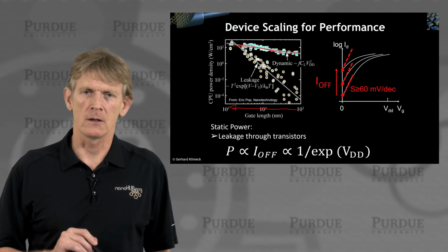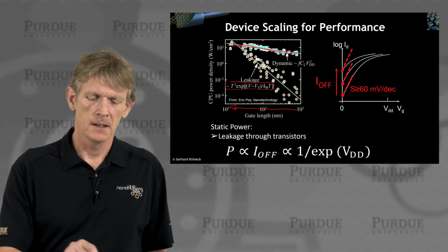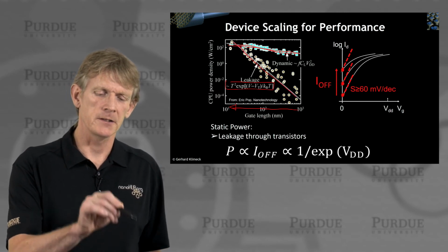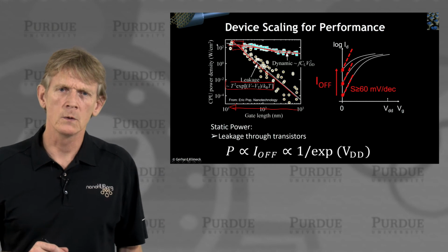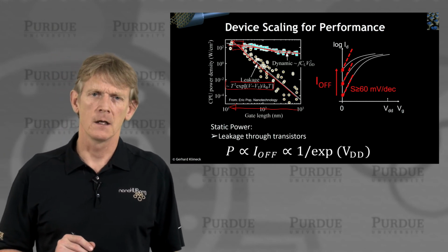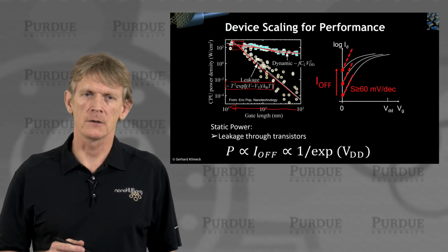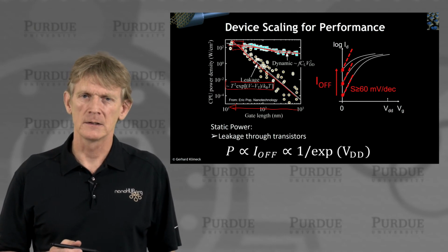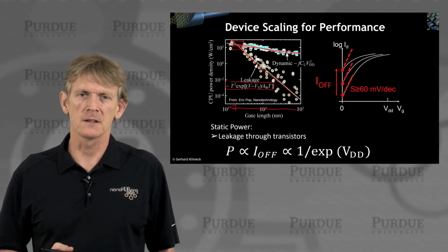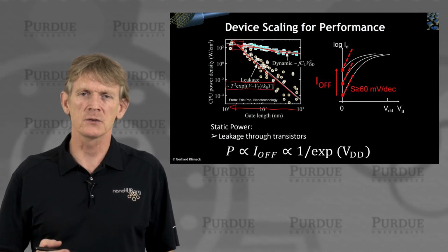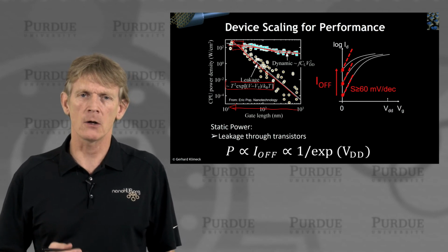But the leakage power, as indicated here, has risen exponentially. And in today's technology, these two are roughly of the same ballpark size. In fact, you can argue the leakage power is larger than the switching power. So that means this ideal, cool transistor from 30 years ago that only consumes power when you turn it on and off is now consuming power all the time.